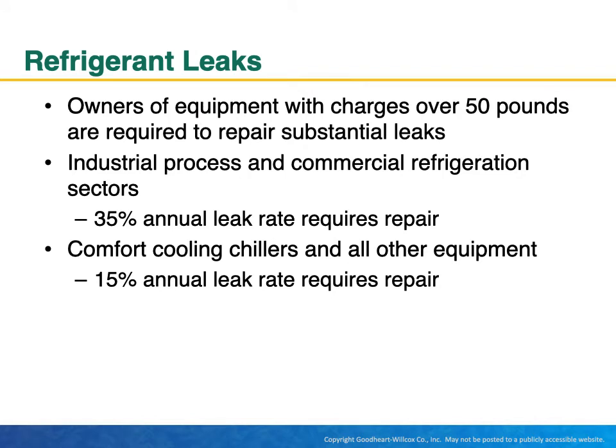Refrigerant leaks. Owners of equipment with charges over 50 pounds are required to repair substantial leaks. Industrial process and commercial refrigeration sectors, 35% annual leak rate requires repair. Comfort cooling, chillers, and other equipment, 15% annual leak rate requires repair.